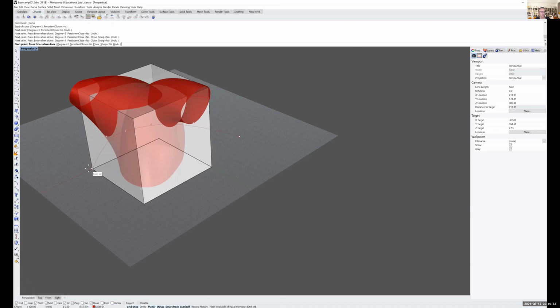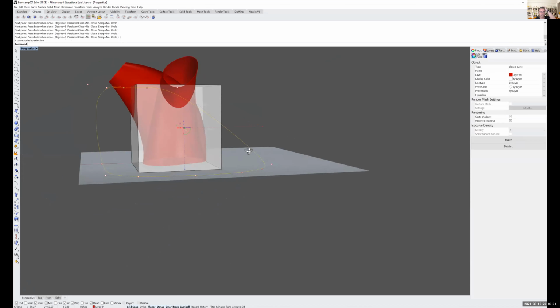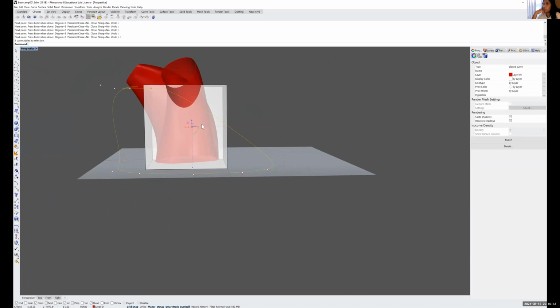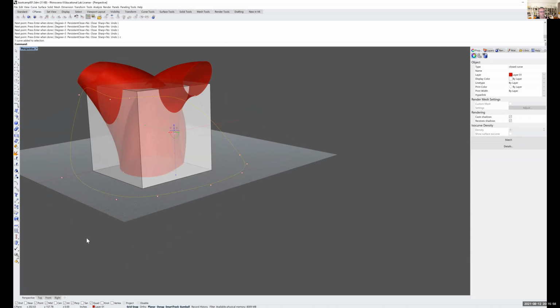It's going to potentially snap to things, and I'm going to intentionally snap to things to make it do it. That's not flat anymore. I think that's because of that. That was the problem this whole time. Yeah. So make sure you turn off near, but there might be, and this is the thing, even mid command.